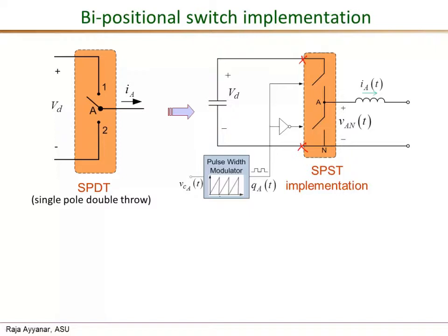And similarly, the pole current needs to be non-pulsating, a non-switching, continuous DC current for DC-DC converters. Those two conditions are represented by this large capacitor across the two positions and this inductor in series with the pole. As we analyze various converters, we'll see that in all power converters these two conditions are always met.